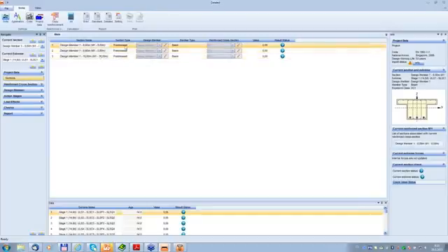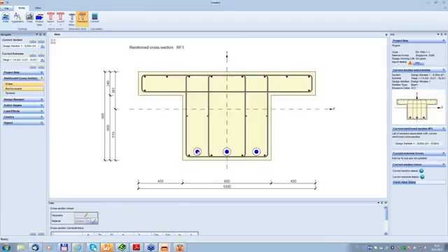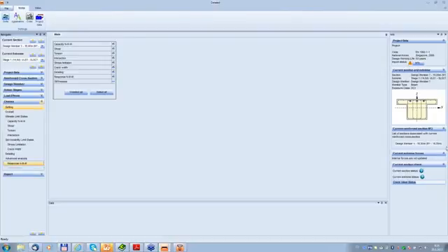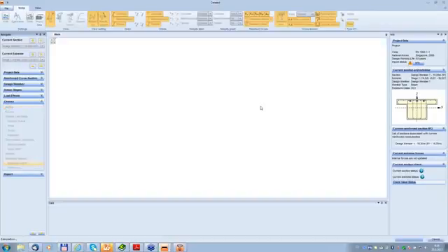The same program as you see in the first presentation of pre-stressed beam. You see here we have 3 sections which are with tendons. Here is the tendon, and I can select another one which is above the support, for example. This one is above the support, and it is already reinforced, and I can go to checks, for example, to response, and I see the response is calculated.